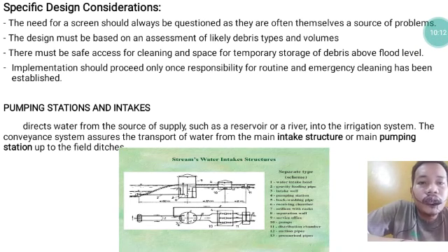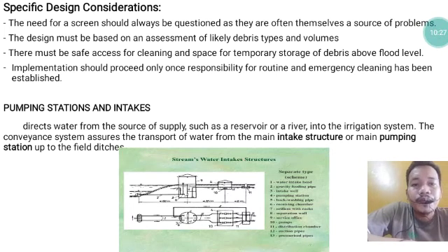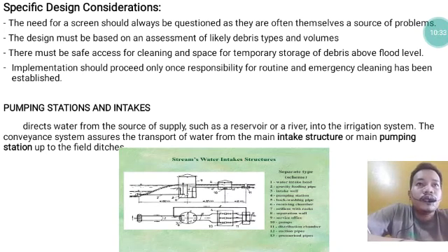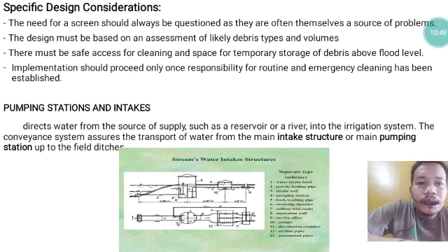Specific design consideration. The need for a screen should always be questioned, as they are often themselves a source of problems. The design must be based on assessment of likely debris types and volumes. So hindi basta maglagay ng screen kung alam mo namang you know that there's a lot of rubbish or what other materials or debris. There must be safe access for cleaning and space for temporary storage of debris above flood level.